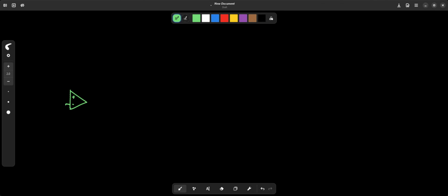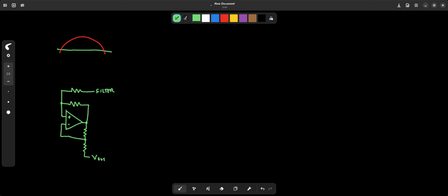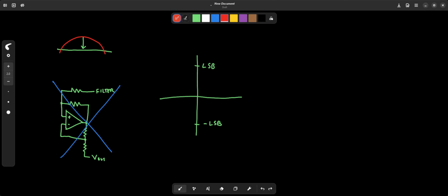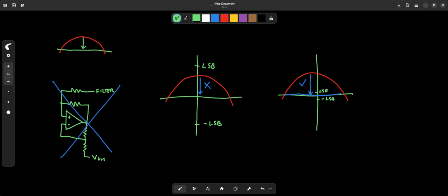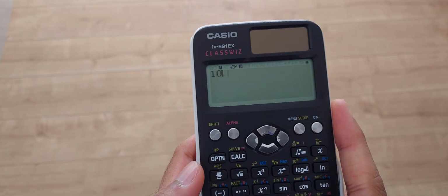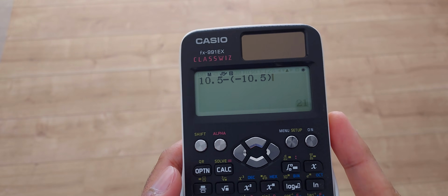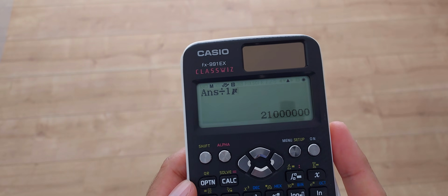If perfect compensation is not possible, it might be time to explore other ways to correct the DAC's raw INL. As I learned while working on the AD5791, a DAC's INL can only be internally corrected if the magnitude of the INL error is much larger than the DAC's LSB size. While the raw INL error is currently on the order of hundreds of ppm, a correction down to sub-ppm levels requires sub-ppm or microvolt settability. With the plus or minus 10.5 volt references, that needs a 20 million count resolution.